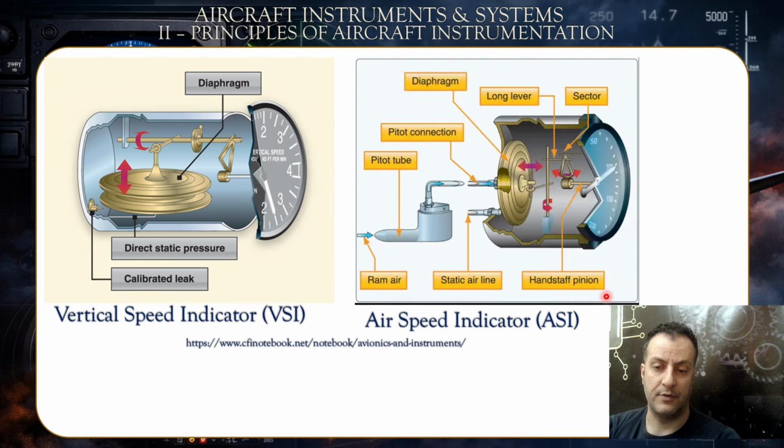Airspeed indicator. Now, for the ASI, how does it work? Again, for the pitot-static system, everything like the ASI, VSI, and the altimeter, the three of them are connected to the pitot tube. Okay? Now, the pitot tube receives ram air, or the dynamic air, through that inlet. Okay? It enters via the pitot tube. And then for the ASI, it will start pushing against this diaphragm that has static air locked on the inside of it. Okay? Again, collected from the ground level atmosphere.